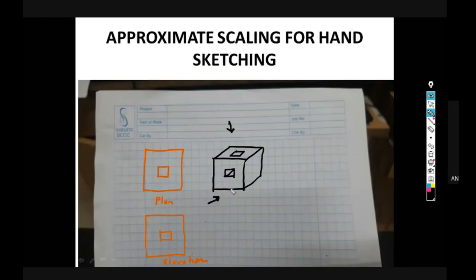So see, if I draw the elevation now for this object, this is, I'm drawing the front elevation. Will it be like this? Front elevation? Yes or no? Yes, sir. But where is this pole? It is behind, so that's why there should be a hidden line, like this. That means this is not matching with my projection. That means this view is not correct.